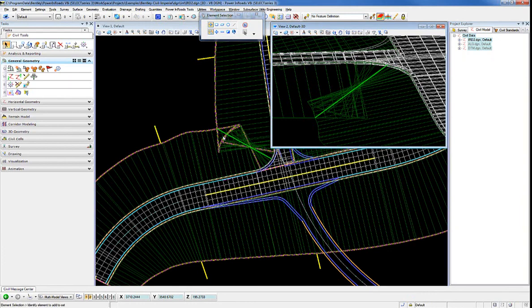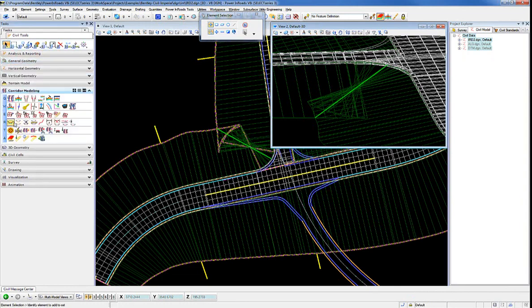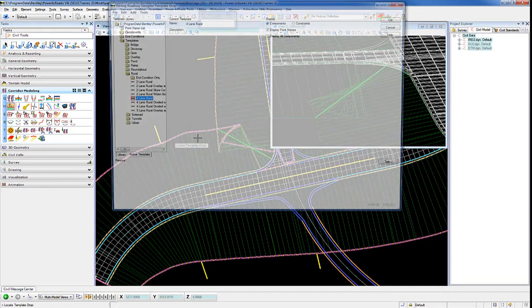Once I have the feature line drawn out here, that's going to give me a line that both of these slopes can intercept, so it can stop there. Instead of going over and overlapping, it's just going to stop at that point. And the way I've done that is in my template drop, actually. If I edit the template drops, I'll show that.